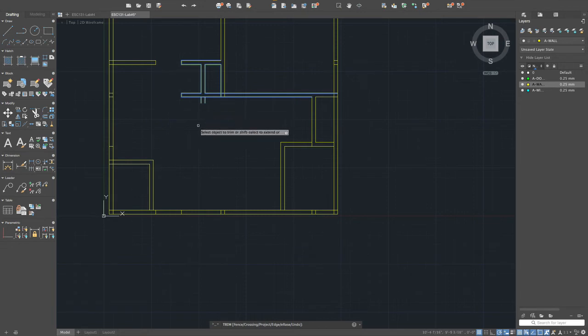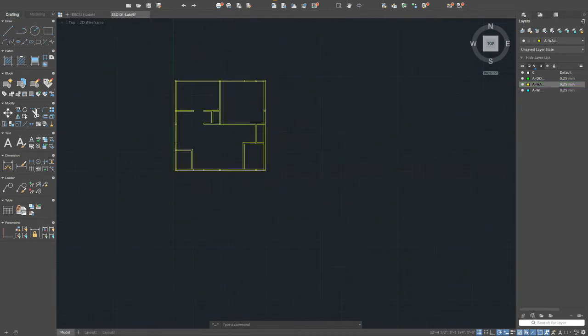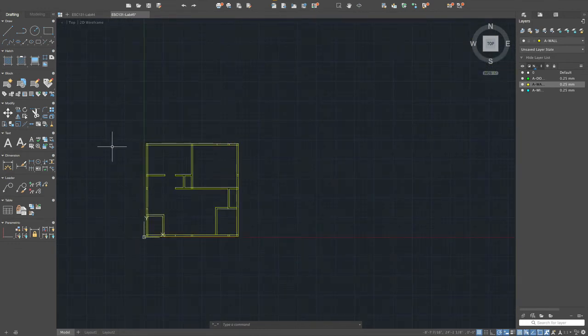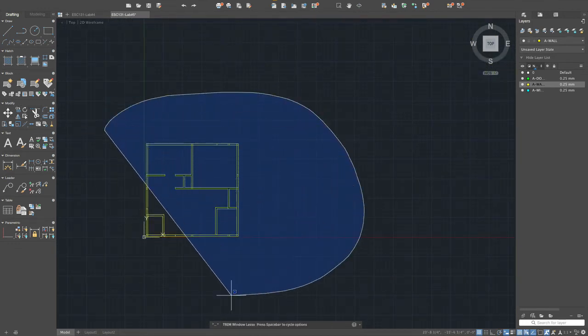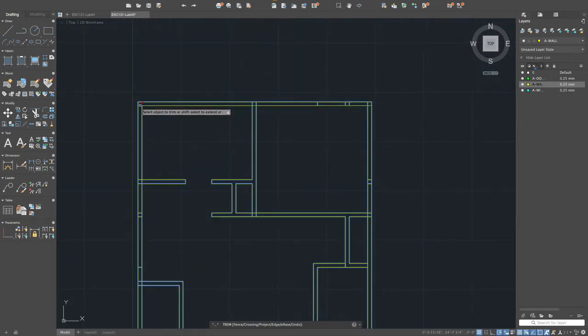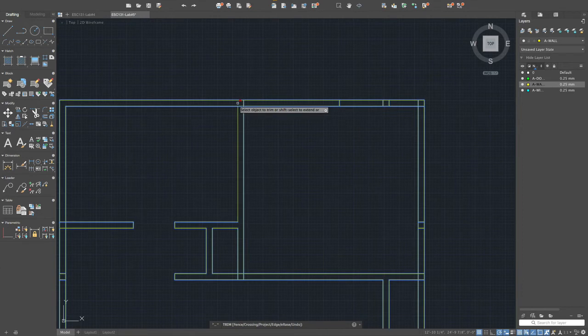Okay. Yep. You got it. Yeah. That's it. So I'll show you probably a few of how to draw the windows and the doors. What you can do is, for instance, okay, let's clean up some more like that, and press enter, and let's trim whatever we don't need. Don't need this, don't need this, don't need this. You can delete those ones later if you want to.